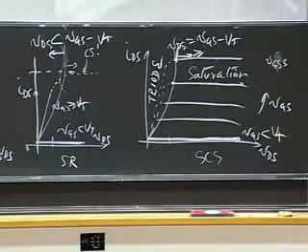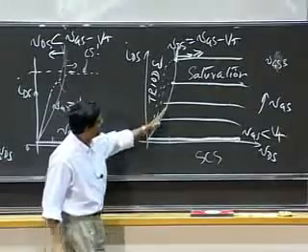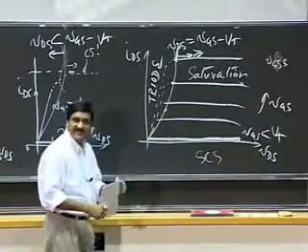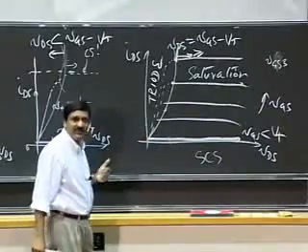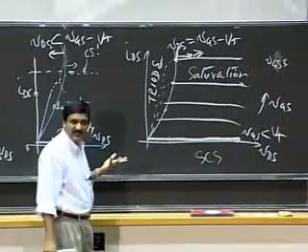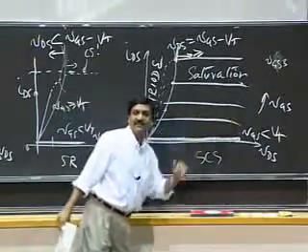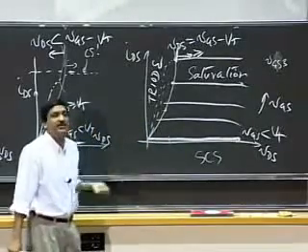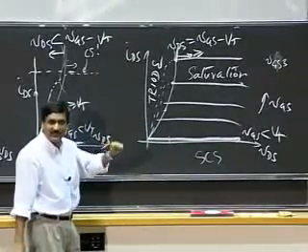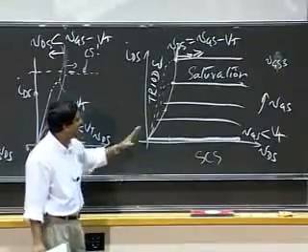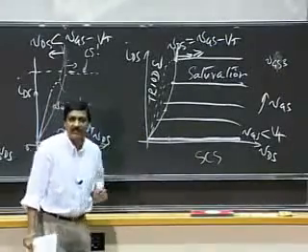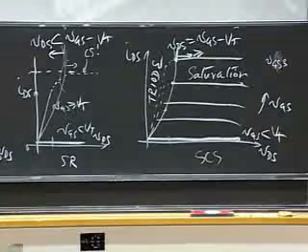This is really very simple. All we're doing is saying that when VDS is increased beyond a certain limit, given by VGS minus VT, the MOSFET begins to behave like a current source. It can't draw any more current. It limits the current to a given value, like a current source. But on the left-hand side of this, it behaves in a resistive manner.